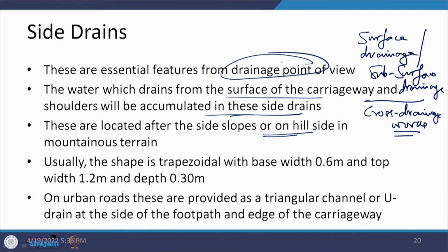Now, these drains are usually trapezoidal in shape with a base width of 0.6 meters, top width of 1.2 meters and depth of 0.3 meters. This is a standard design, but it is also going to depend on the volume of water which is coming as a surface flow.